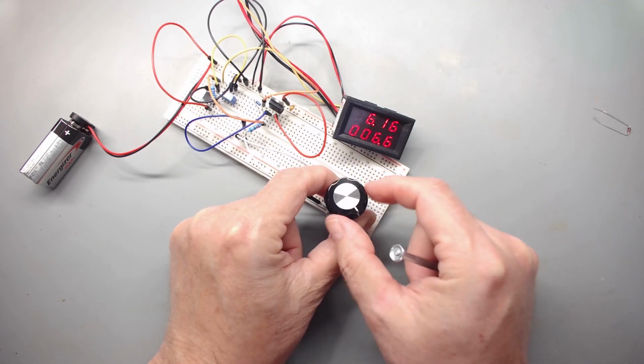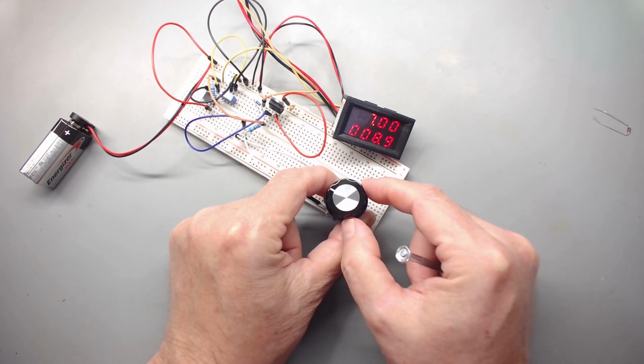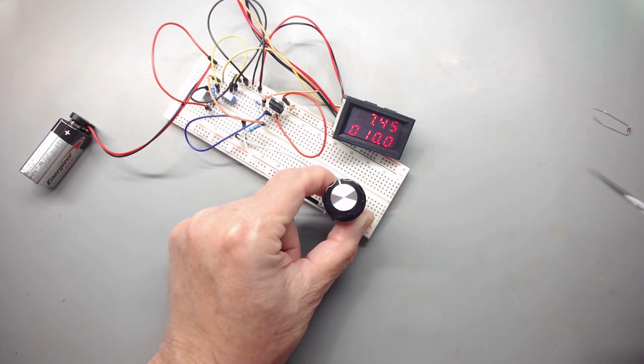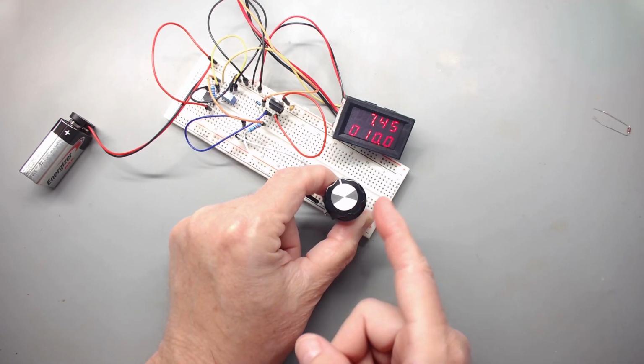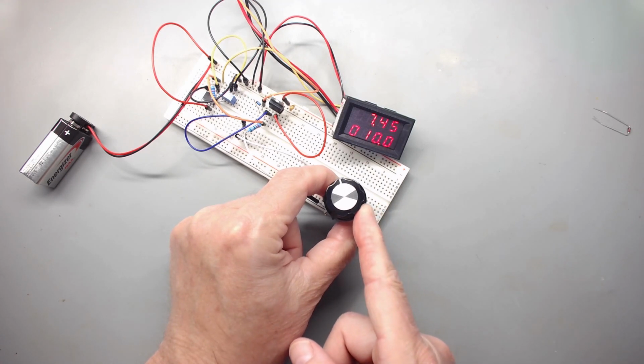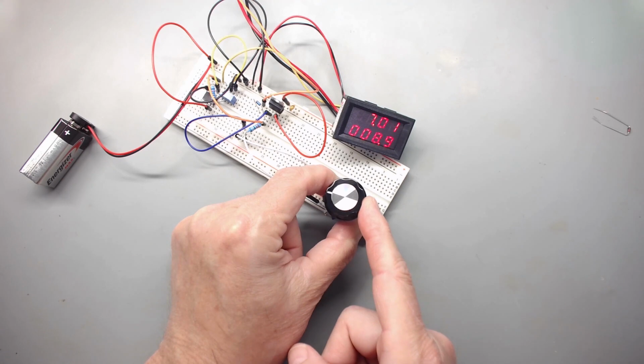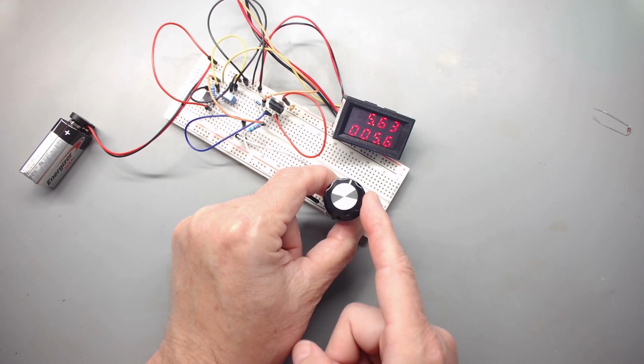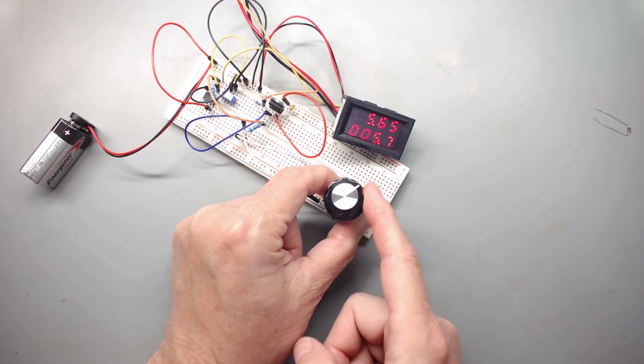So let's take a look at something. Let's go back to 10. Remember our charts showed us that diodes' forward voltages were affected by the current through them. So here we are at 7.545, or in other words, 0.745 volts. Watch as I turn the current down. Watch how much the voltage changes, okay? Now you can see that if the current's bouncing all over, we'd never be able to categorize these diodes. You've got to have a very precise current to compare the forward voltage, and that's why we need that. So this is working very, very well.